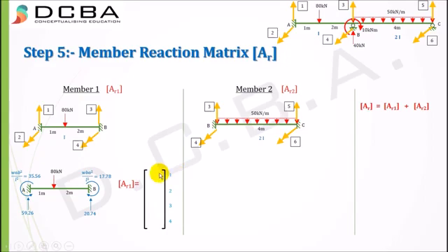So in the direction of 1 it is 59.26, and both the directions are the same, therefore it is plus 59.26. Then 2 is a moment, and this moment is also anticlockwise. Our positive moment is also anticlockwise, hence it conforms, therefore it is plus 35.56.